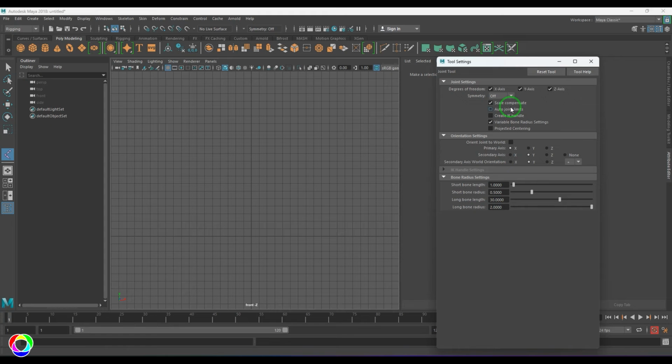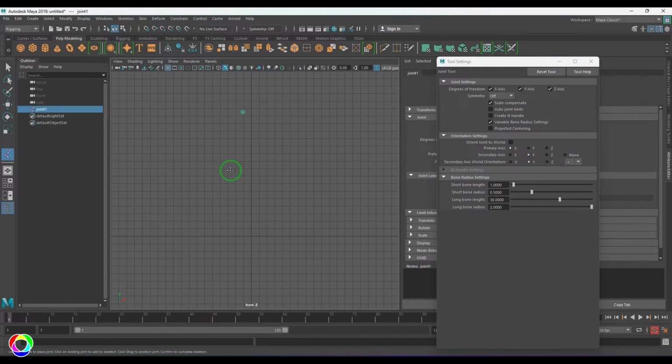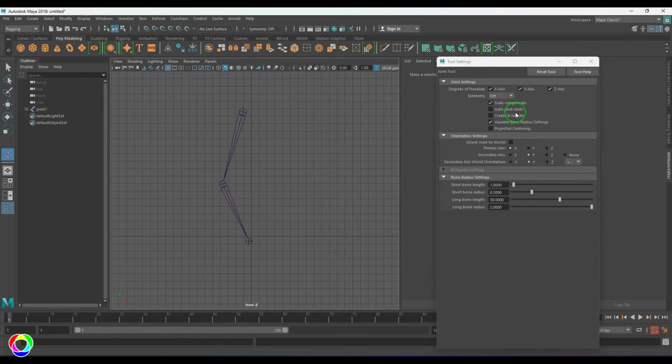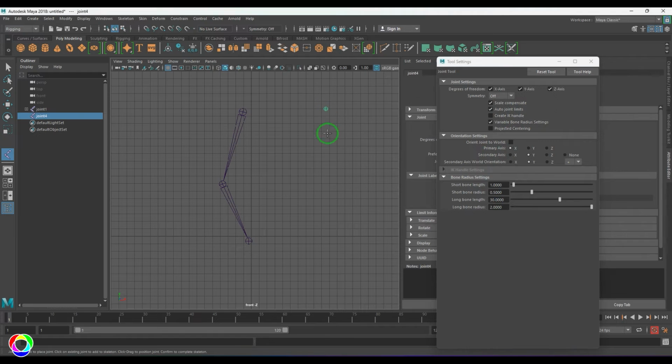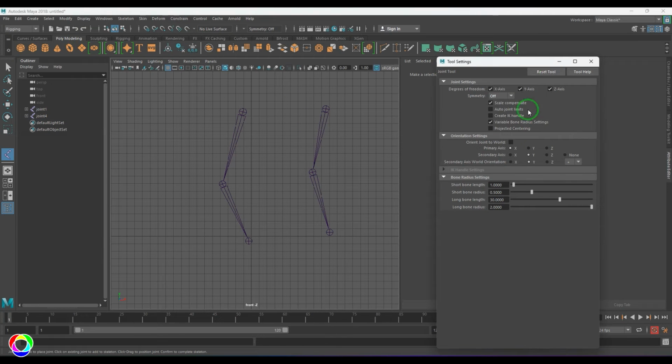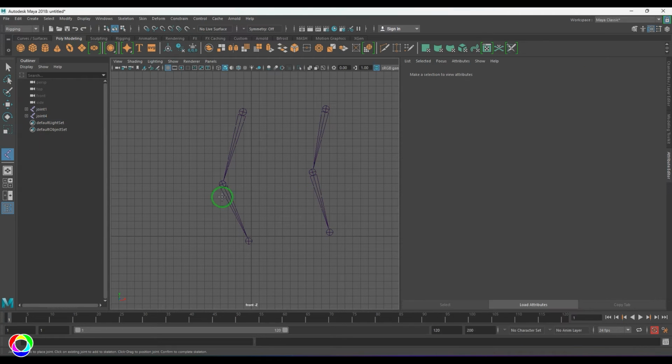And we have the auto joints option here. What that actually does is, when I'm creating this joint chain and slightly bending it for the knee, I'll go to the create joint options and switch on auto joints. Just click and then click there. Auto joints is off, right? So I made it on for this.